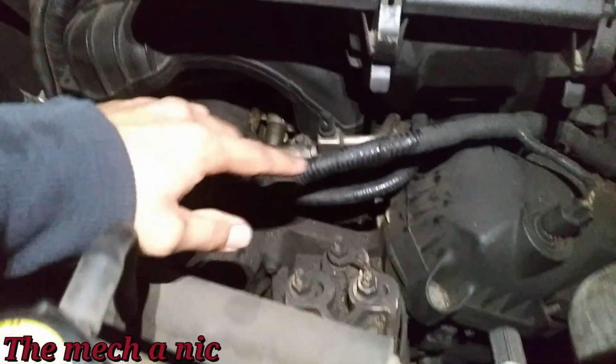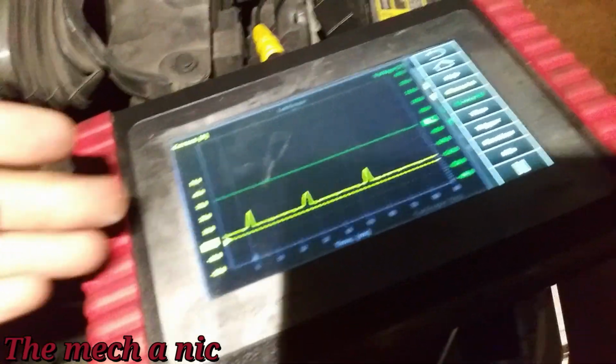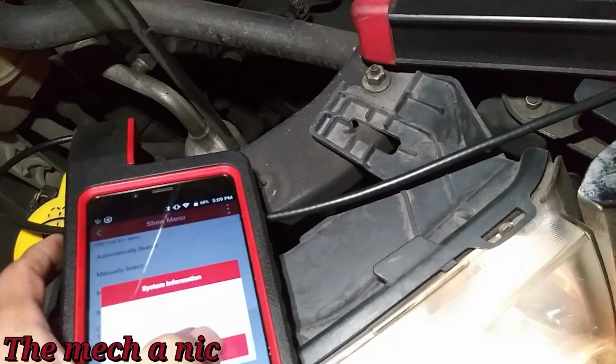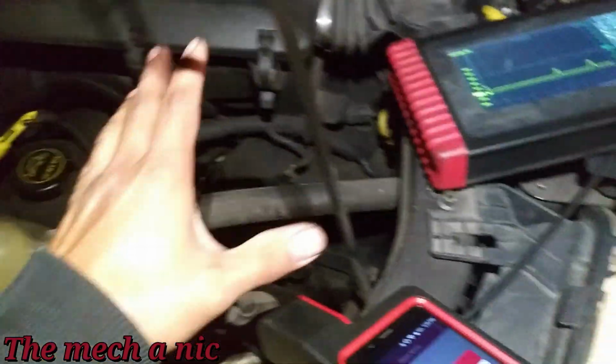Let me get my light. I tried wiggling the harness and nothing happens. I even tried tapping on the fuel injector with my long screwdriver here, and still nothing. That injector is not working. So I'm gonna go ahead and connect the scanner right now, and we can see if there's any misfires present, which I'm sure there are, because this injector is not working right now while it's cold.